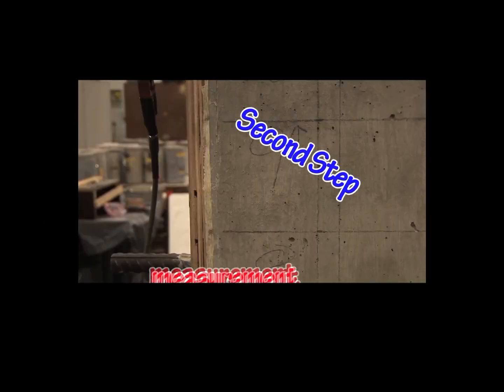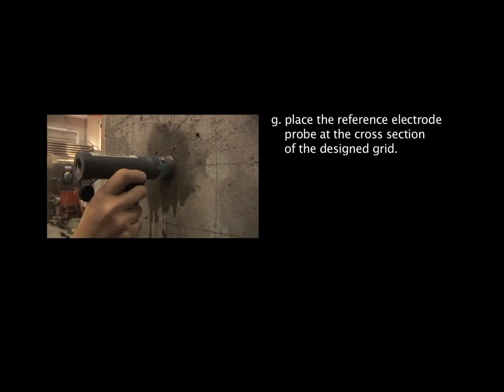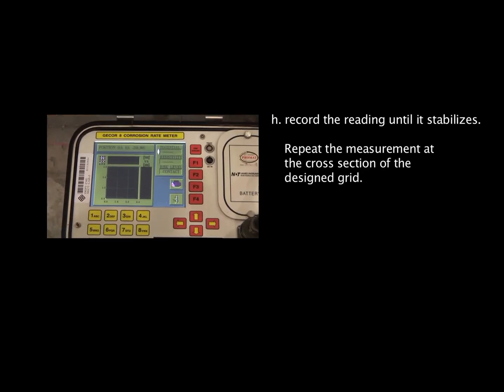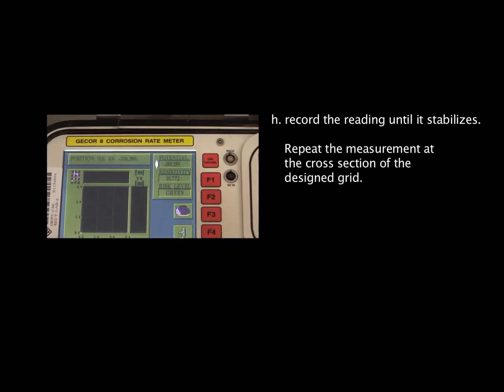The second step is measurement and plotting. F. Design a grid of measurement. G. Place the reference electrode probe at the cross-section of the designed grid. H. Record the reading until it stabilizes. Repeat the measurement at the cross-section of the designed grid.